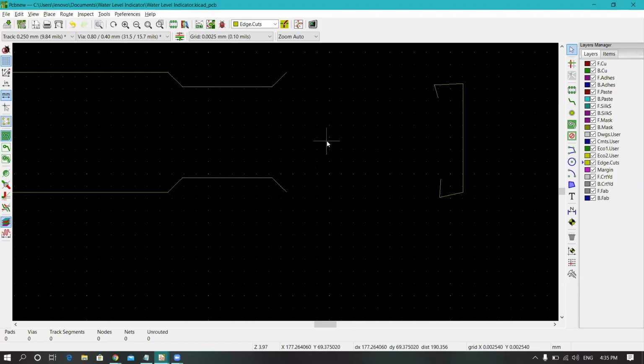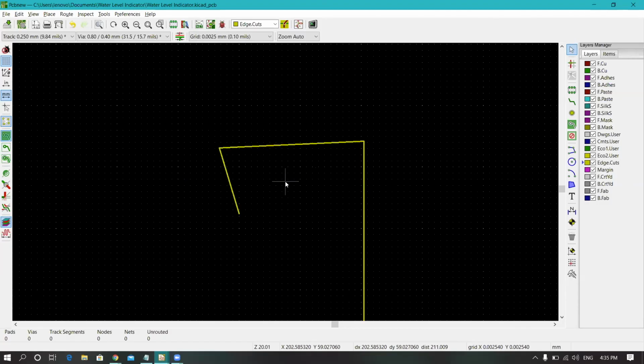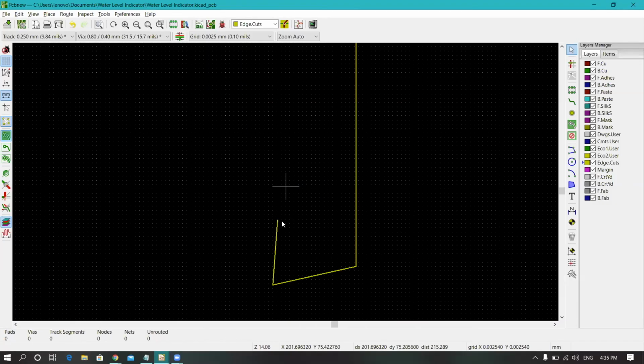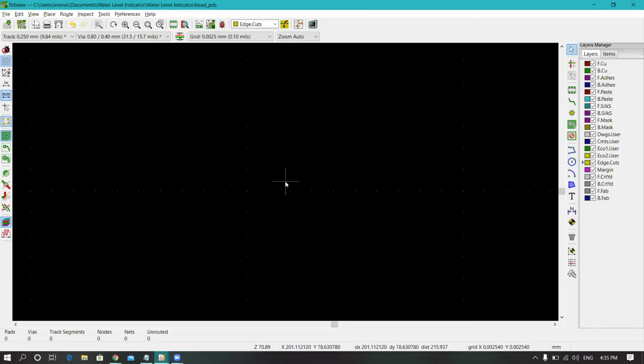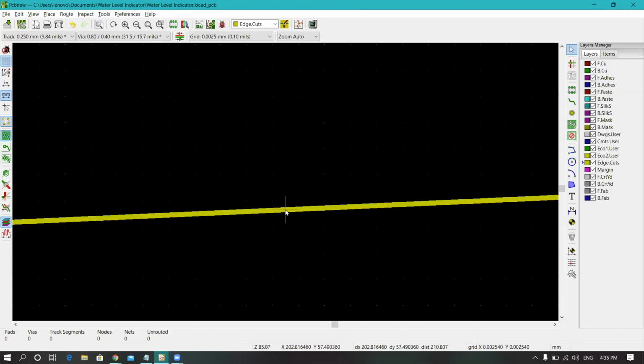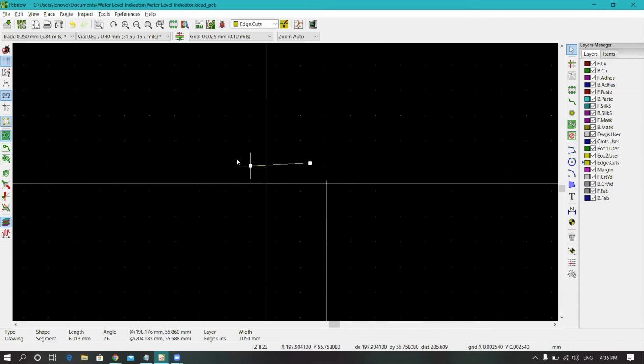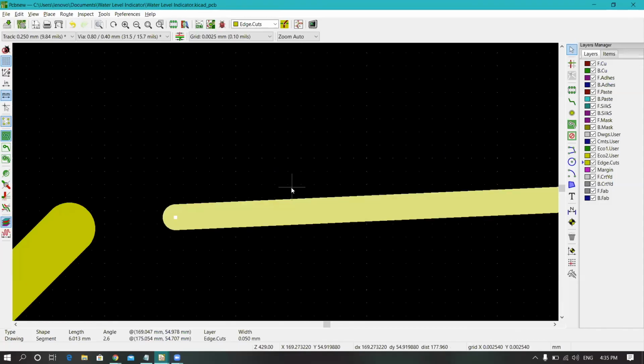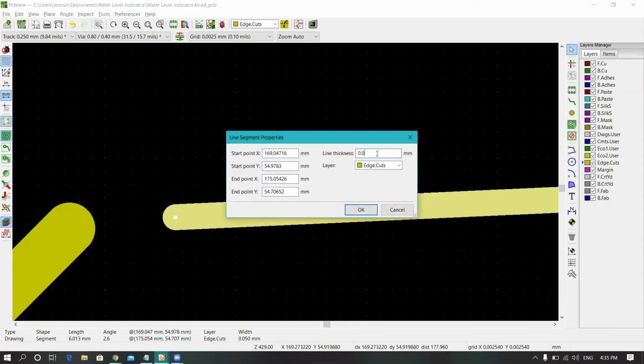Now our PCB layout is somewhat complete. Deleting these two lines. Now we have to make this portion. Taking this line, pressing M and placing from that position to this. Editing this line to 0.1. Straight line. We will have to make 169 of 169.